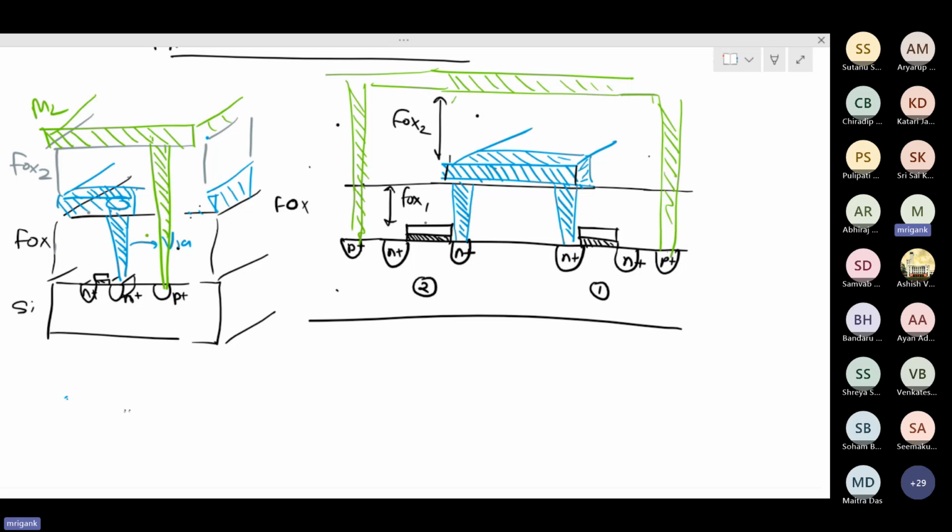So ultimately, all this patterning will also require different masks. So based on your circuit design, based on the layout that you have done, physical layout that you have done, you will have a certain pattern created for the metal 1 layer, certain pattern created for the metal 2 layer. By your design, you define these patterns. And then based on these patterns, the connectivities are done. So this is just to give you a feel of what the actual fabrication process will be. And actually, these connections are made in the physical drawing.